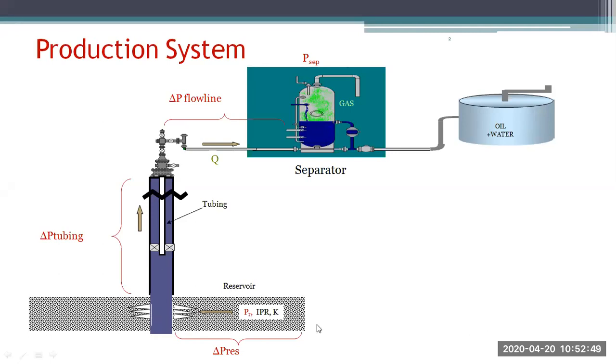So if I talk about inflow, that will only and only have the reservoir pressure and the bottom hole pressure. No surface pressure or tubing pressure will come into it, okay? And the flow rate will be from the reservoir to the bottom hole. Because first we are going to understand whether my reservoir is able to produce or not. Then only I will understand all these concepts, whether it is coming out or not. If it is not coming from here to my bottom hole, then my total well is failed. So I need to operate it at such pressures and flow rates that it is flowing continuously throughout the life.